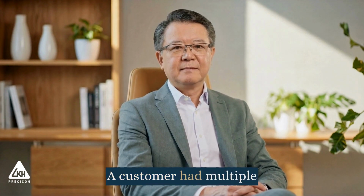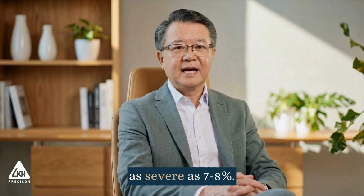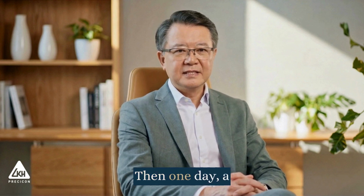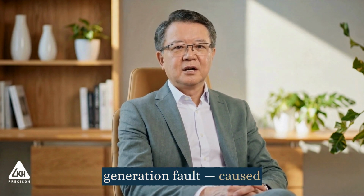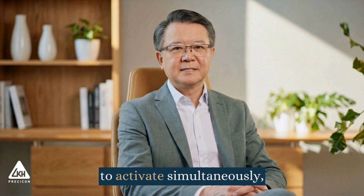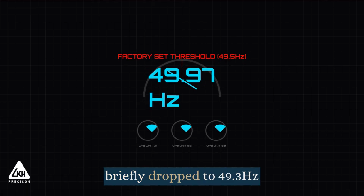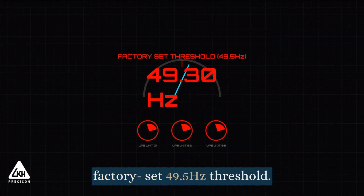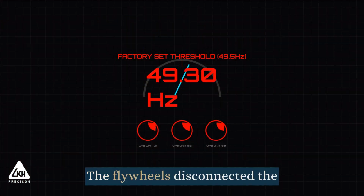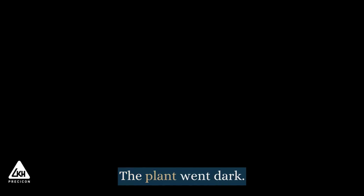Case study 3 is a cautionary tale. A customer had multiple flywheel UPS units that had successfully handled dips as severe as 7 to 8%. Then one day, a minor 3% voltage drop from a power generation fault caused all their flywheel units to activate simultaneously. Because the grid frequency briefly dropped to 49.3 Hz, below the OEM's factory set 49.5 Hz threshold. The flywheels disconnected the grid. Their stored energy depleted. The plant went dark.